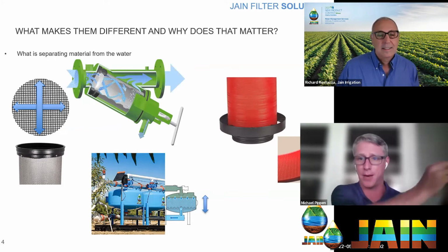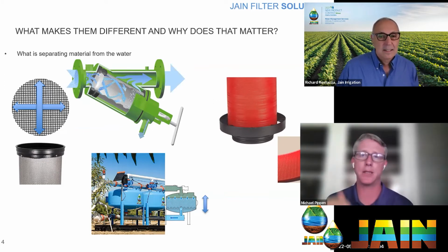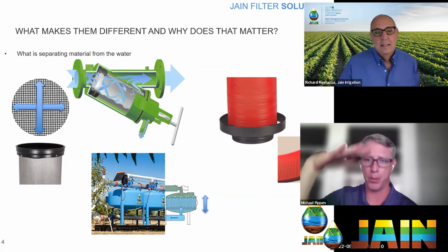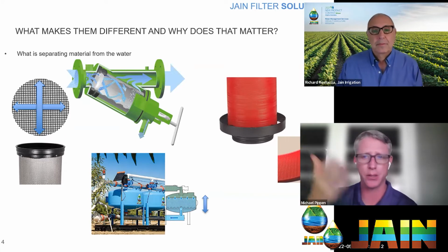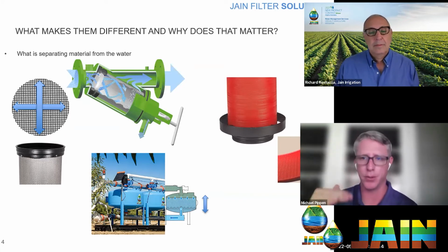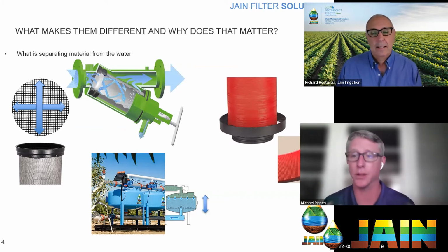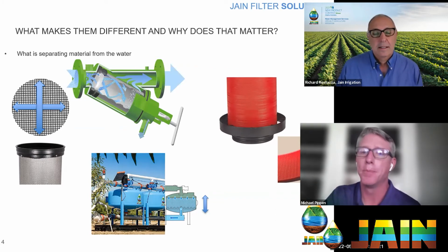It finds a buddy and it gets together and then it causes a problem. So that sand filter gives us an added depth to where it's harder for that organic material to push through. It adds not just surface area, but also some capacity. You can just catch more stuff before it's clogged, is what a sand filter can do.